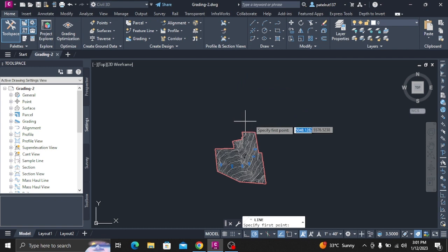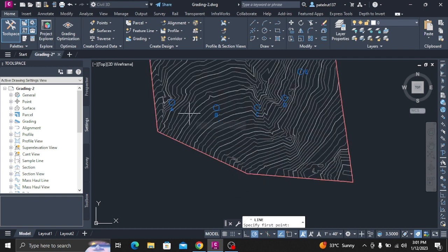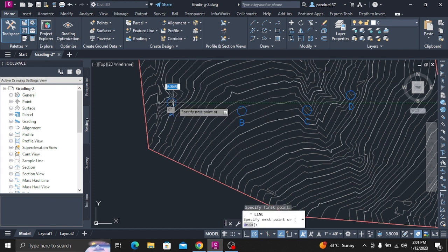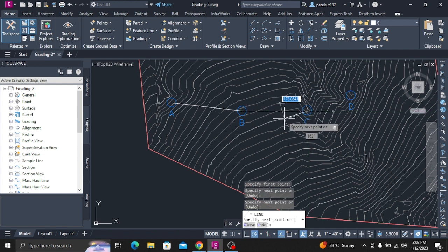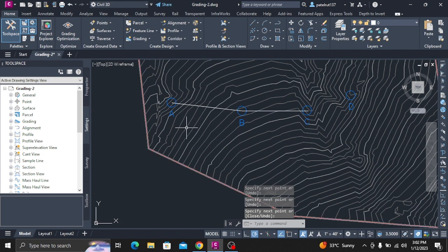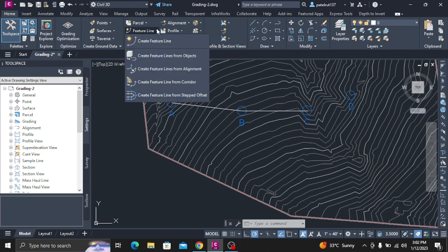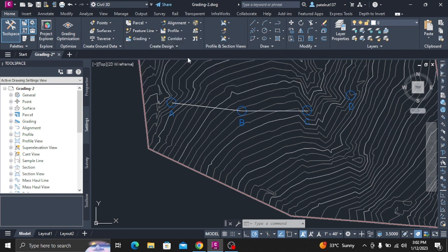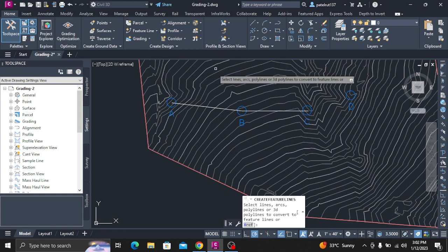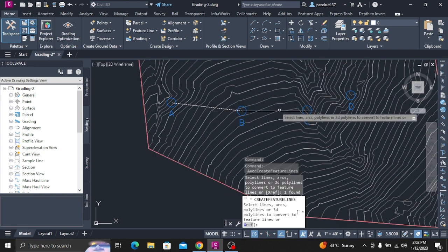Name the feature lines. In the drawing, select feature lines AB and BC. Right-click. Click Apply Feature Line Names. In the Apply Feature Line Names dialog box, click. In the Name Template dialog box, for property fields, select Next Counter. Click Insert. Click OK. In the Apply Feature Line Names dialog box, place the cursor at the beginning of the name field. Enter ABC. The name field should contain ABC, Next Counter. Click OK.